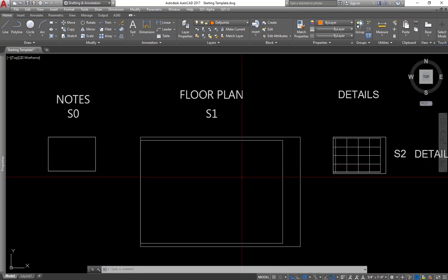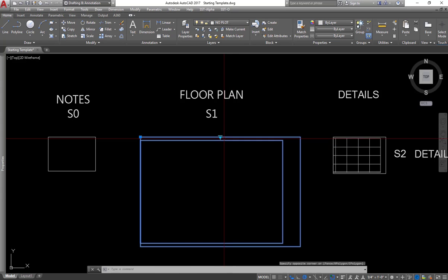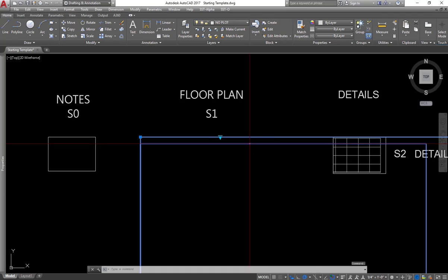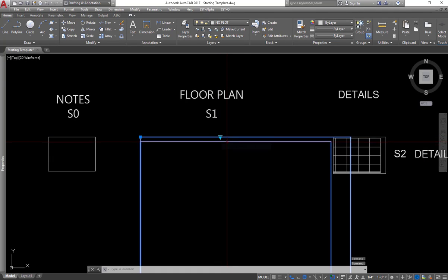So what size sheets to use? What we're going to be using is 24 by 36, and that's really typical for any kind of construction, engineering, architectural sizes. It's really manageable in the field. 1/4 inch is easy to scale. If you get into like 1/8 inch equals a foot or 3/16 equals a foot, it's kind of harder to see.